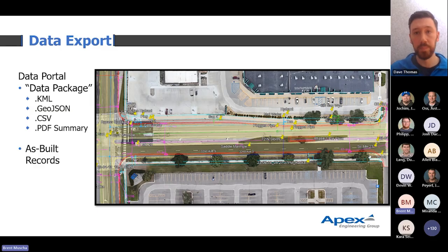And Dave, you're working on, and you've already got some integrations with some e-ticketing services as well. Can you touch on that and how that works? Absolutely. From our experience and understanding, a lot of the e-ticketing vendors capture location information with lat-long coordinates. We are right now connected with a system called FleetWatcher, where they use hardware that goes in the truck and the paver, and it creates a geofence. When those geofences cross on a project, it stamps a lat-long coordinate on the ticket. With FleetWatcher, we're able to take that lat-long coordinate and automatically convert it into a station alignment and offset.